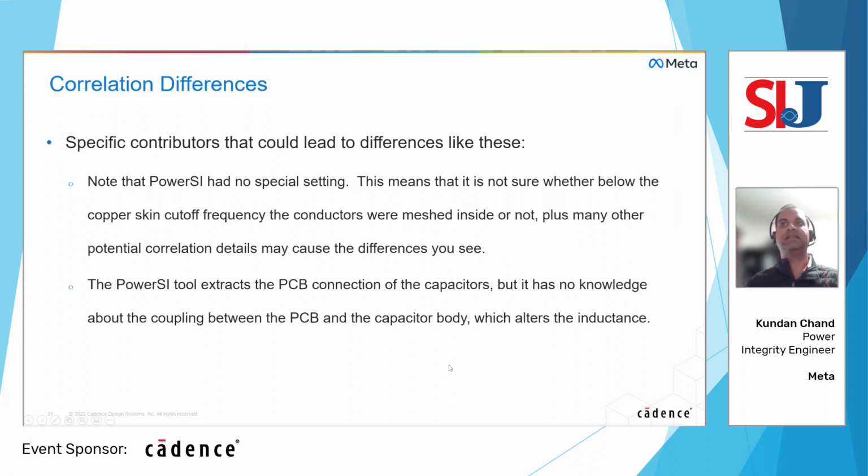The other was, since we are using the capacitor vendor S2P models in PowerSI, the tool is extracting the PCB connection of these capacitors, but the coupling between the capacitor body or the capacitor S parameter and the PCB may not be captured by the PowerSI tool. So that could also be related to some of the differences.